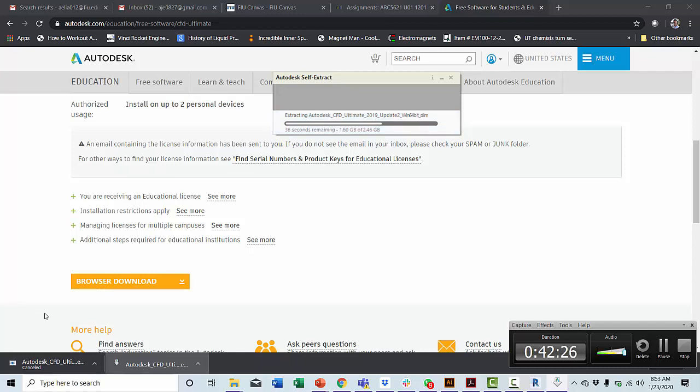You guys can reference your book and see the general forms and design strategies for natural ventilation. But the book examples are very basic shapes. So you are going to have more custom shapes depending on your site and the way you design, especially if you have really fluid and curvilinear shapes. It's hard to understand how the wind will react because it's not so straightforward. By running CFD, you can get a much clearer picture before you start constructing the building, of how wind might react and how you can minimize loads and energy usage that you would otherwise have to use for ventilation or HVAC.